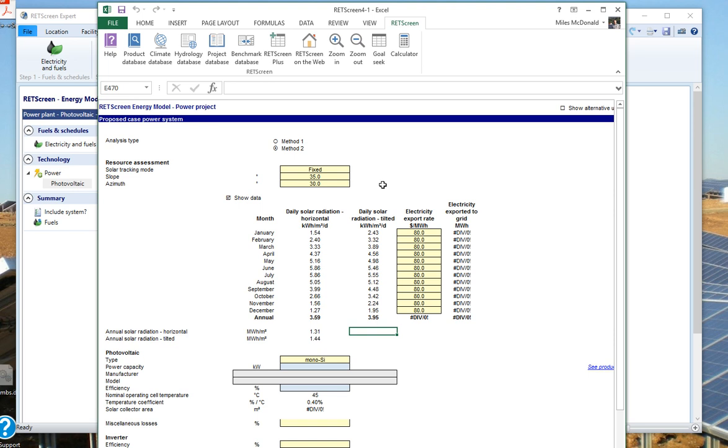Something else important to know about azimuth: magnetic North Pole is different than true north. Also, it's important to know that the magnetic North Pole does move and change relative to true north. So when you're using a compass to determine the direction, a correction must be applied so that true north and true south are accurately identified.